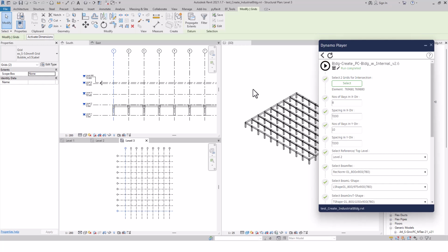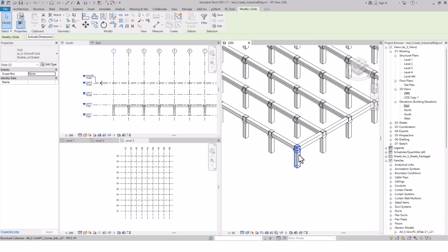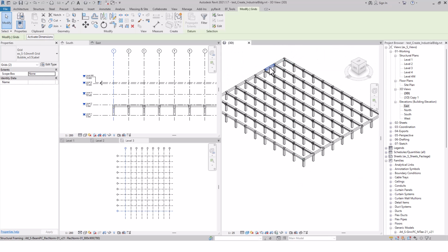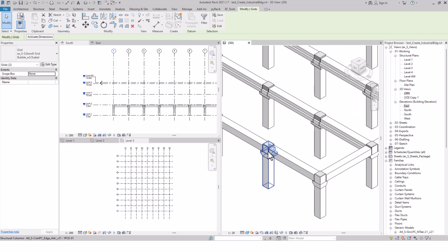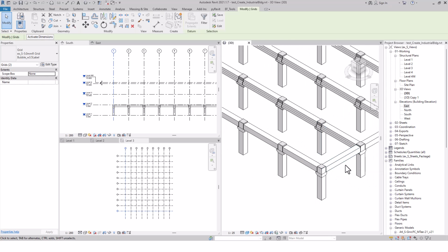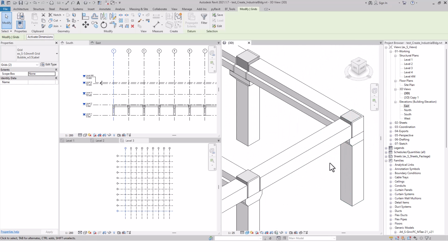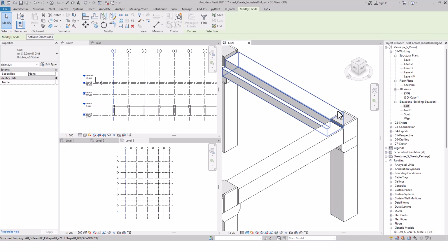Just wait a while, then we are going to see the structural columns from level 2 to level 1. So we have 3 main types: corner, edge, and intermediate. Then we have the beams. This is the L-shaped beam, and this is the inverse T, and those are the normal rectangular beams. We'll place correctly into the model, right? Okay, so this is the 120 cut off, so after that the slab will be filled up, right?